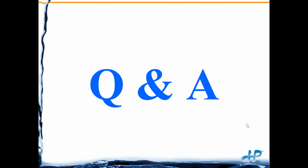Alrighty, just waiting for the questions to come in here. Okay, that one is just a partial question. It just says, not for wastewater? I guess I would need to know at what point in the presentation that was chosen for. If you're referring to whether the contacting style is ideal for wastewater, you can use it in wastewater, but make sure you use a 4 electrode and probably one of the higher cell constants, the 1.0 or the 10.0, because of the range in which your wastewater is going to be.